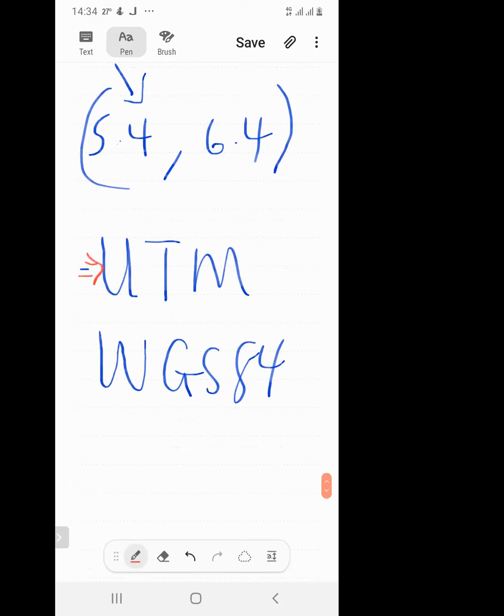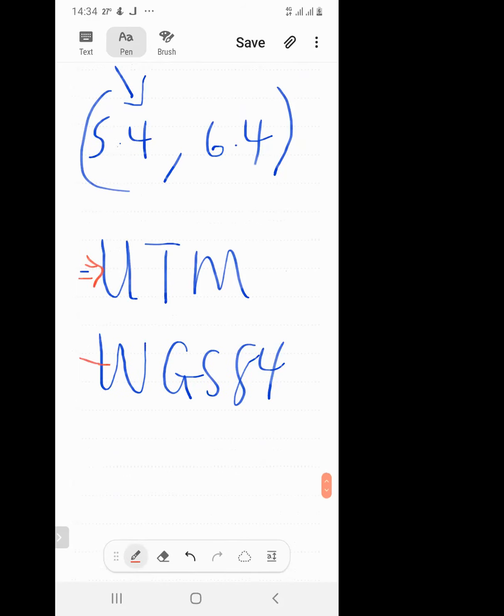So the UTM actually is a popular projected coordinate system. In GIS, you'll be seeing projected coordinate system and then the geographical coordinate system. Whichever way it's said, if you understand it, and they are using another term, you still know they are trying to talk about projected and then spherical, geographical coordinate system: longitudes and latitudes. That's WGS 84. And then the UTM is the projected one.